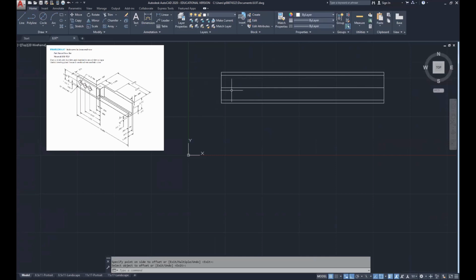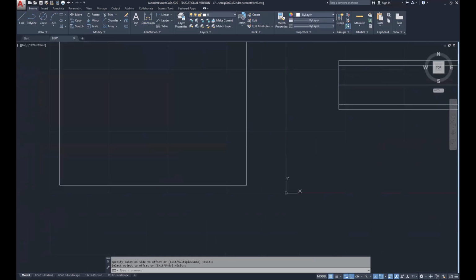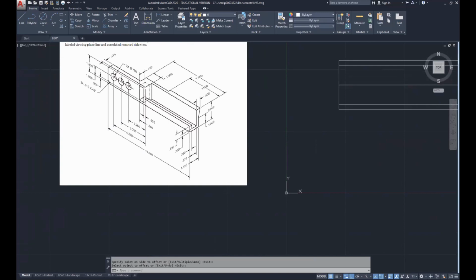On this one here, we're going to be using a lot of dimensions to the centers. We're going to have to establish some locations. If we follow the dimensions along, you'll notice from the right-hand side, coming over to here, we have a 4 and a 7 along the back side. And then we have a dimension coming from that back side forward 1, which is going to get us to this edge here. And then all the dimensions come from here over this way. So in order to work on these dimensions here, I'm going to have to work on the right-hand side.